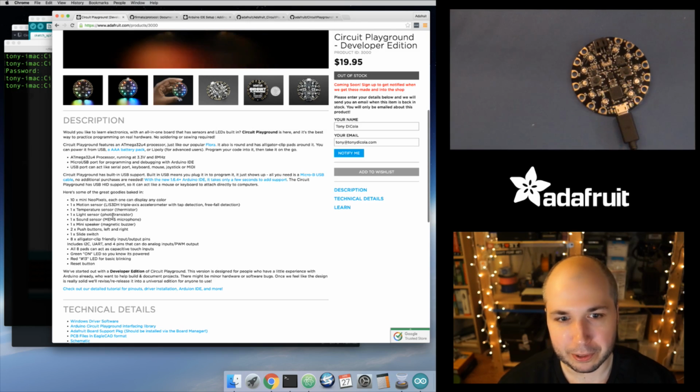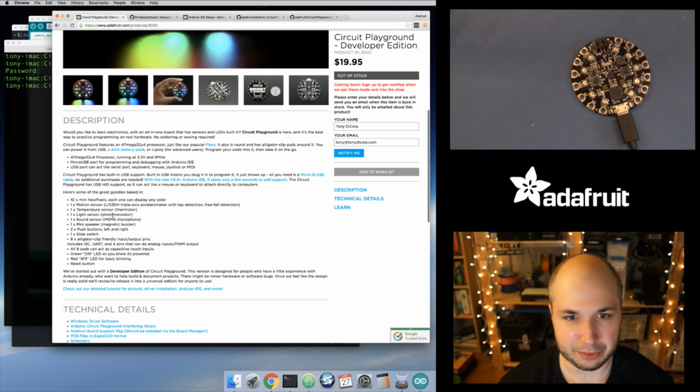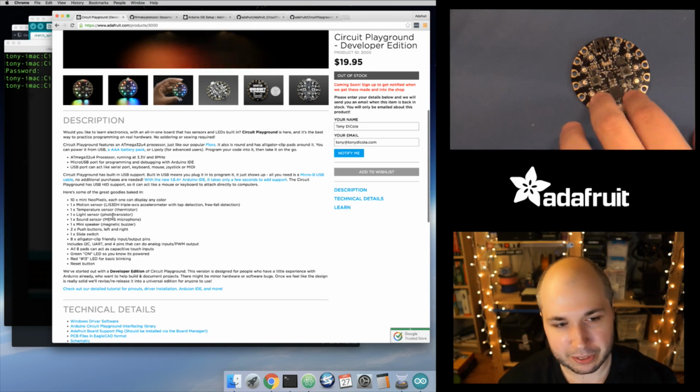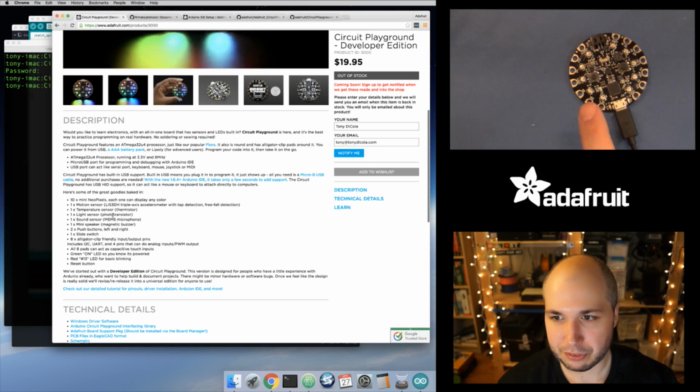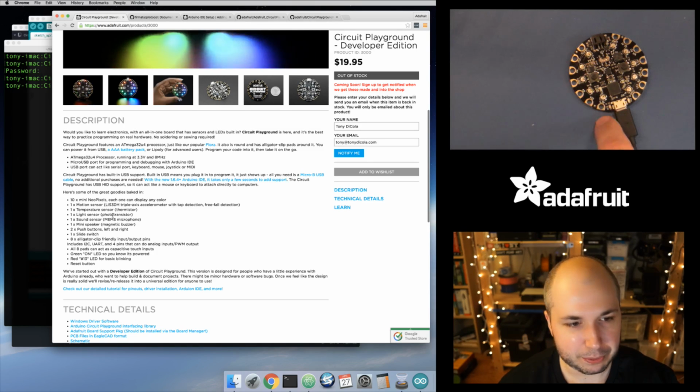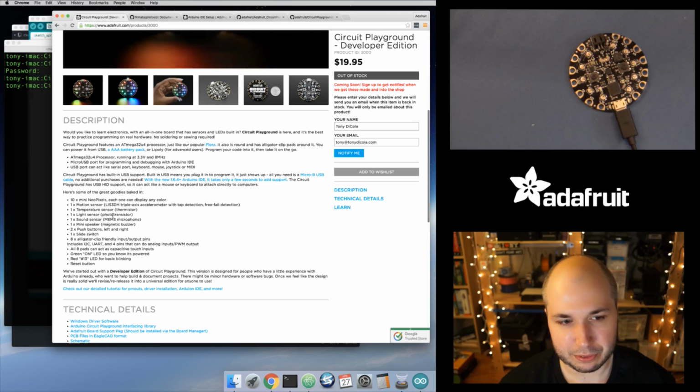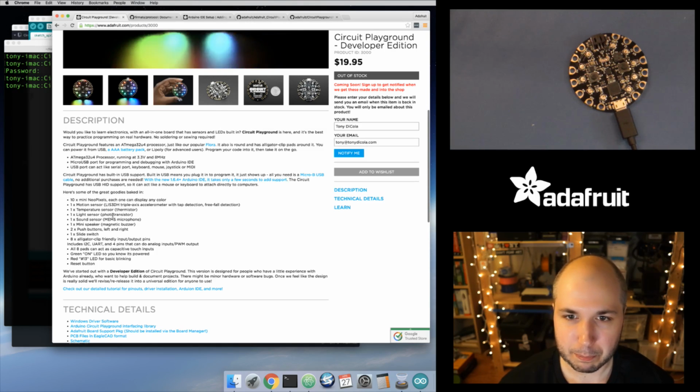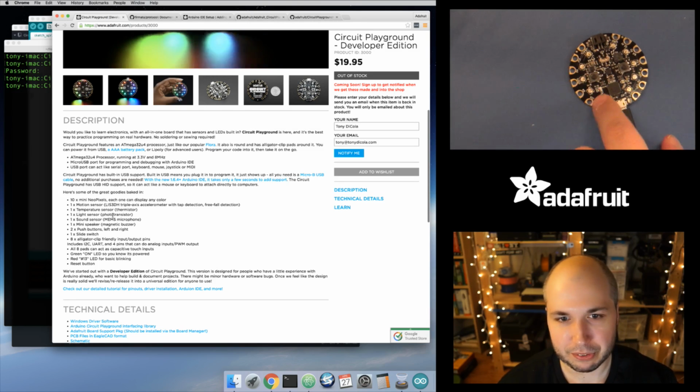So like if you tap the board, it can pick that up, and you can treat that as maybe like a button press to do something. Then it has some analog sensors. So there's a thermistor, which is a temperature sensor. It's basically a temperature sensitive resistor. There's a light sensor, just a phototransistor. So both of those output an analog signal. They change their resistance based on the things they're sensing. So as the temperature changes, the resistance changes.